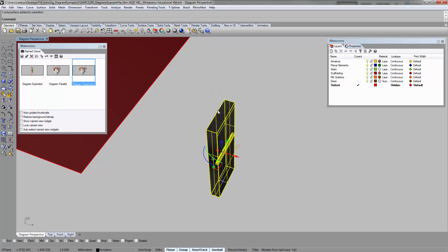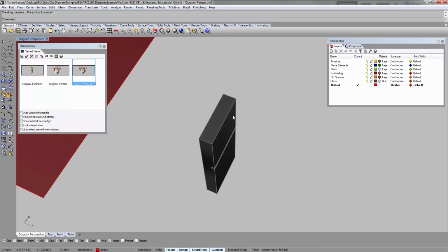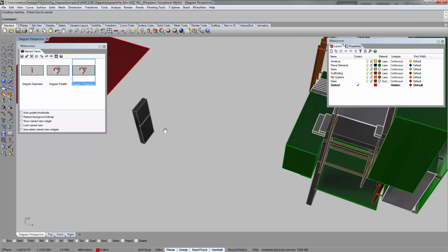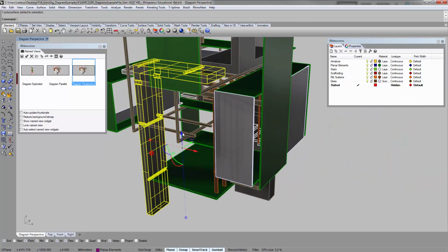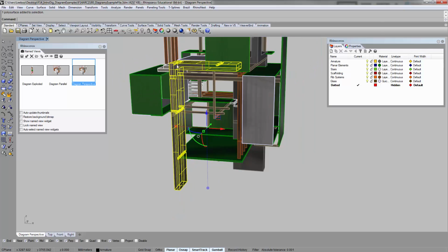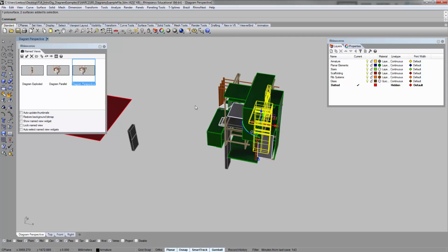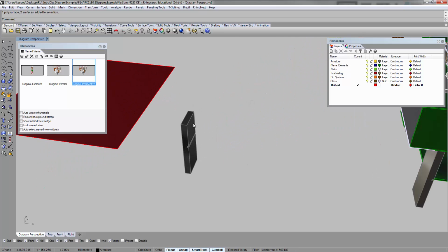The first way, and usually you can do this, granted your geometry is clean enough, is you can just run a command called cap. And it will ask you for surfaces or polysurface to cap, and just select them and enter, and it will fill it up automatically. But sometimes you'll run into more complex walls that just can't be filled normally.